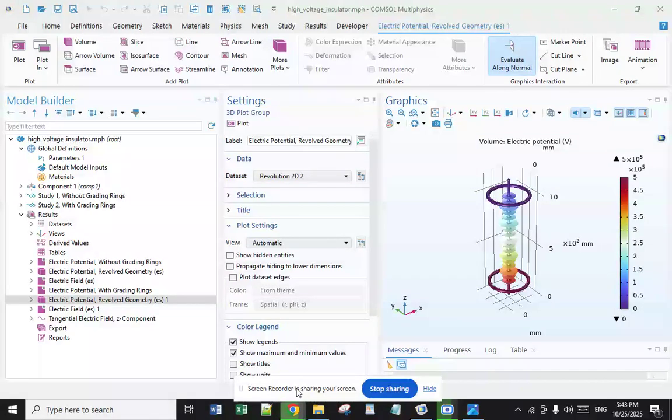How to choose the right insulator? To choose the right insulator for an electrical system, several factors should be considered, such as the type of current used, the load the insulator will support, the environment in which it will be used, among others. It is important that the insulator has the appropriate dielectric strength and rigidity for the electrical system in which it will be used. Low voltage insulators are essential elements in any electrical system operating with voltage below 1000 volts.